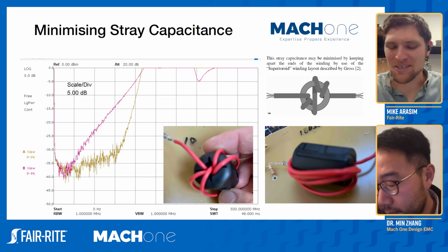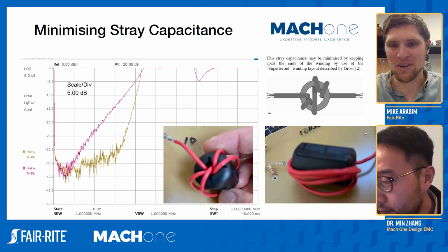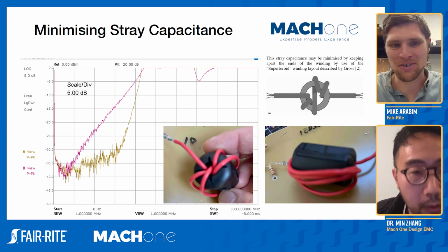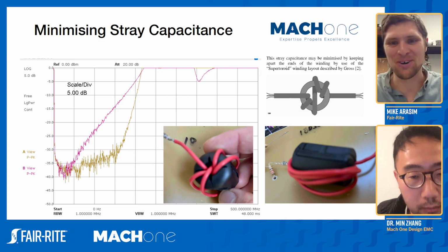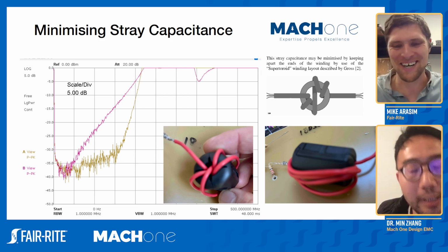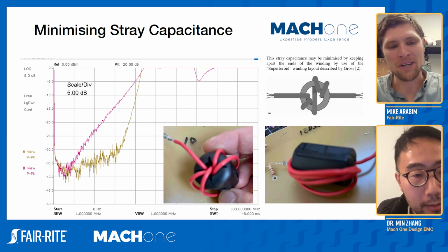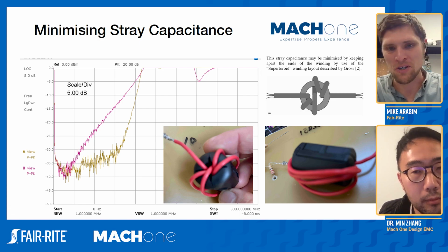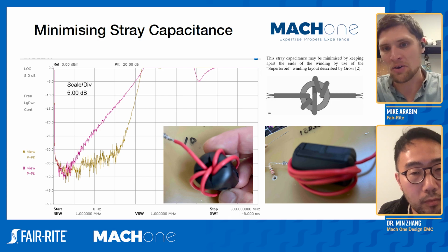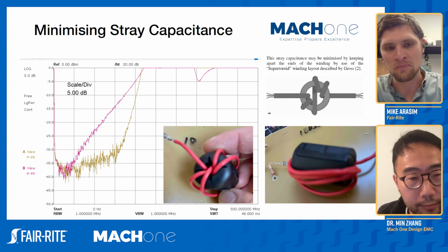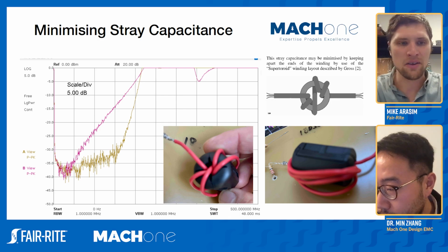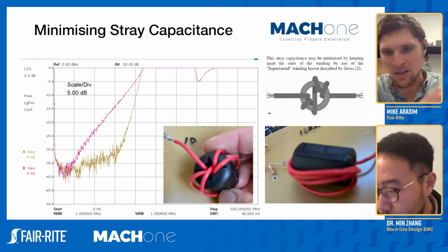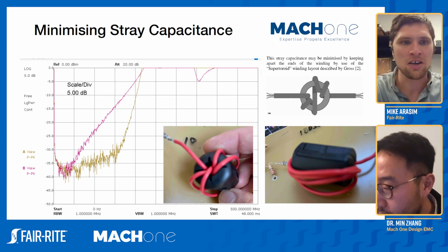It can be. So, the very obvious, without being too funny, thing to consider is whether the inner diameter of your core can actually fit multiple turns. But at the lower turn counts, and especially at the lower frequencies, typically more turns is going to be better. You'll get a higher impedance value, but that does come with some drawbacks as you start increasing that turn count.